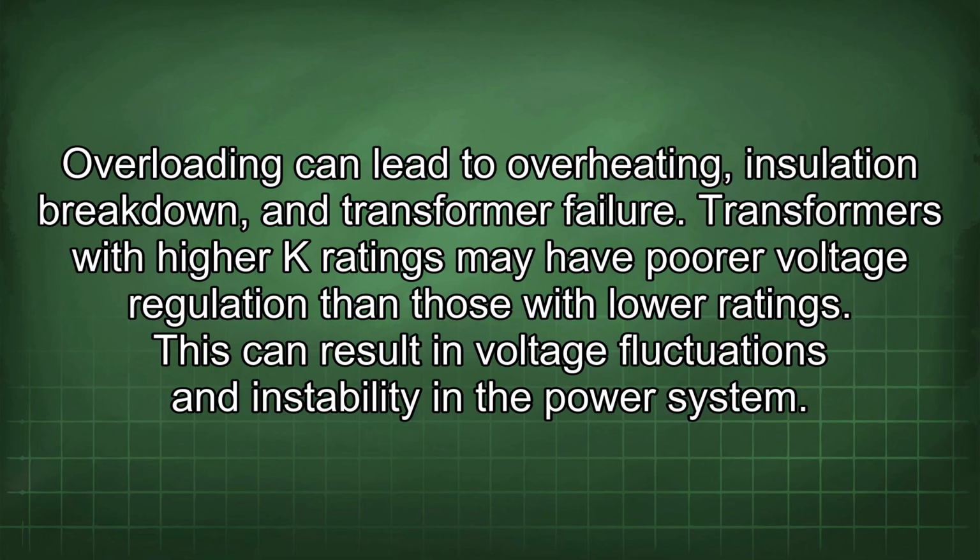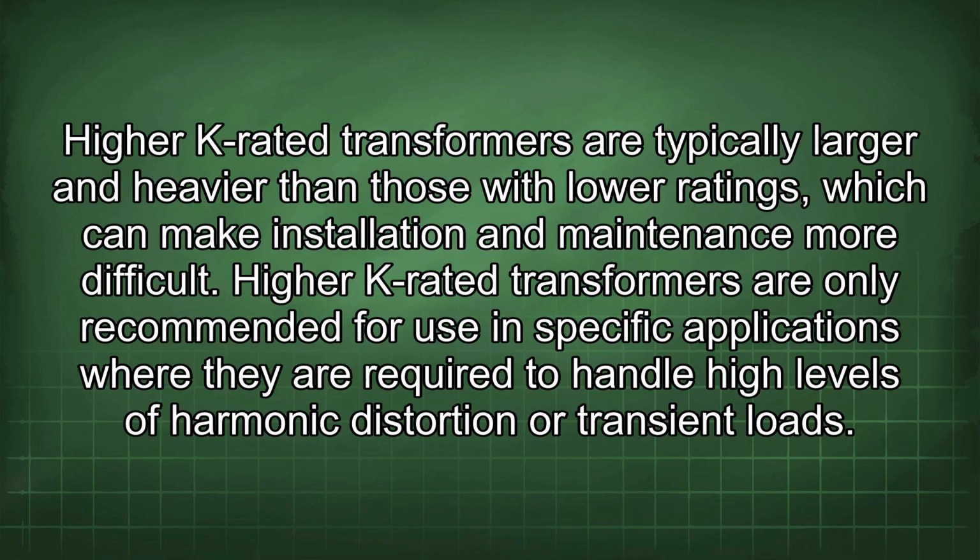Transformers with high K ratings may have poorer voltage regulation than those with lower ratings. This can result in voltage fluctuations and instability in the power system. Higher K-rated transformers are typically larger and heavier than those with lower ratings, which can make installation and maintenance more difficult. Higher K-rated transformers are only recommended for use in specific applications where they are required to handle high levels of harmonic distortion or transient loads.